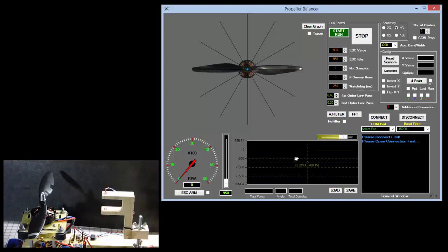And then if you hit the Control key, you can pan it. So I made it very, very interactive. It should make it extremely simple for us to compare graphs and also take measurements from a vibration perspective to see how well your balancing is working.